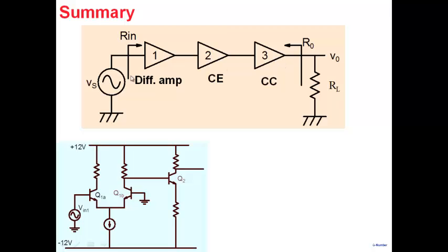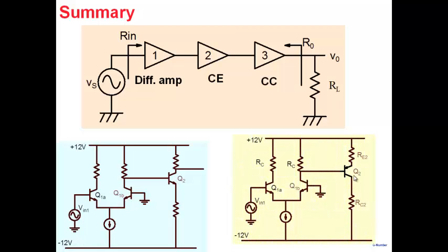For a bipolar, we had chosen a simple bipolar differential pair, a common emitter amplifier, and a common collector amplifier as the output stage. The design of the simple differential pair is straightforward, but an NPN common emitter doesn't give us gain when interfaced, so we had to take a PNP common emitter stage here.